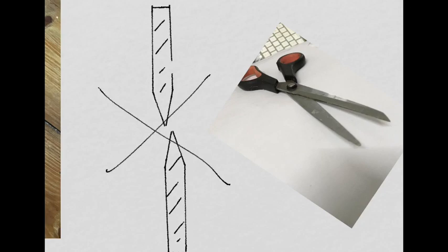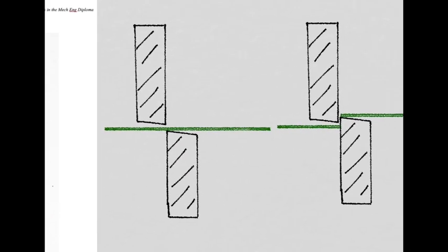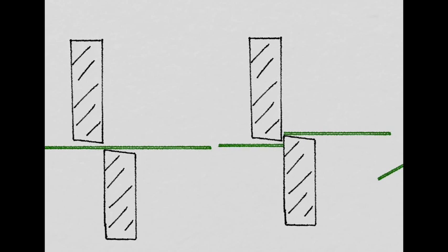They don't cut as knives. Instead, they look a bit like this over here. So when you sharpen a pair of scissors, you ensure that you get an almost flat surface there with a keen, well-defined edge over here, and you normally give it a slight relief angle like that and like that. The green two lines indicate the piece of paper, and that is the two blades approaching the piece of paper, ready to cut it. And here they have cut the piece of paper.